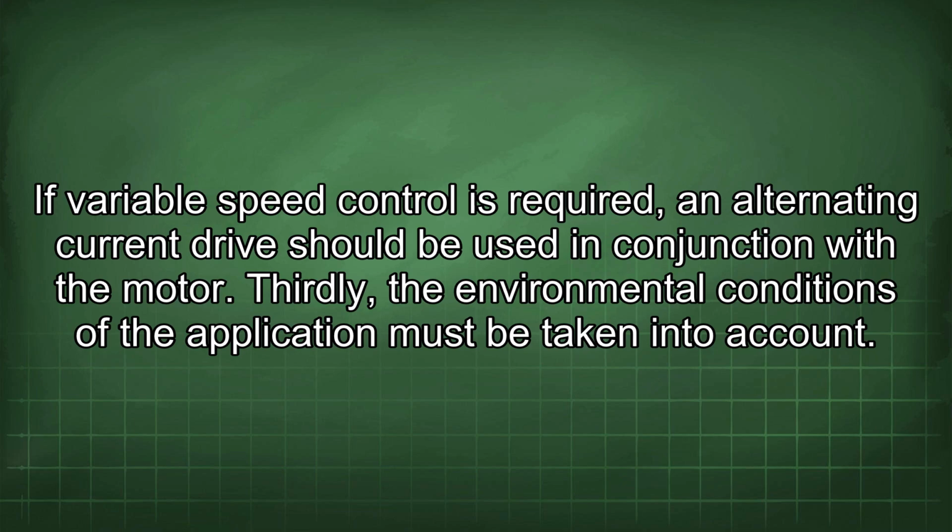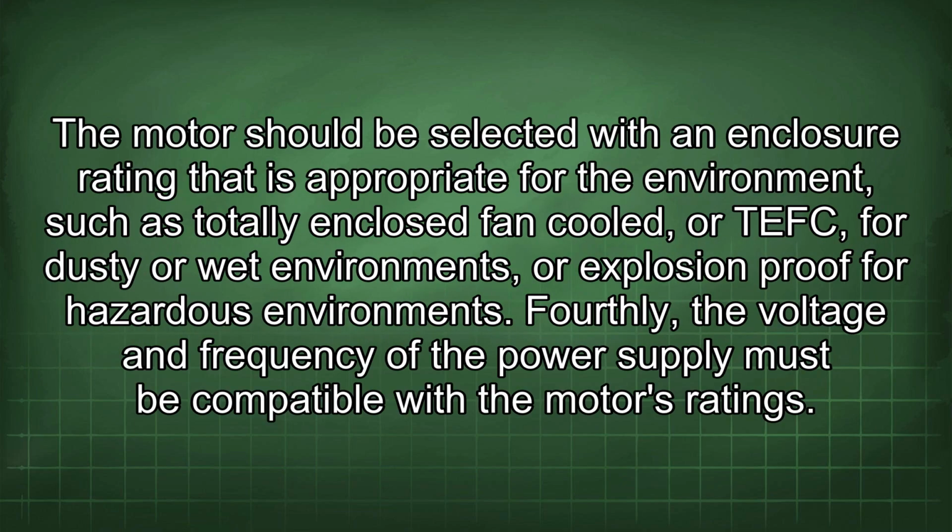Thirdly, the environmental conditions of the application must be taken into account. The motor should be selected with an enclosure rating that is appropriate for the environment, such as totally enclosed fan-cooled or TEFC for dusty or wet environments, or explosion-proof for hazardous environments. Fourthly, the voltage and frequency of the power supply must be compatible with the motor's ratings.